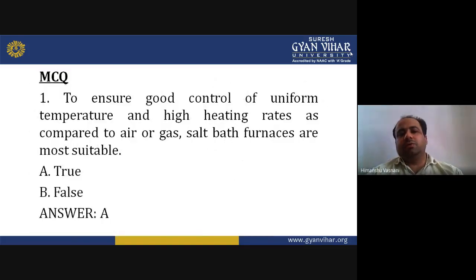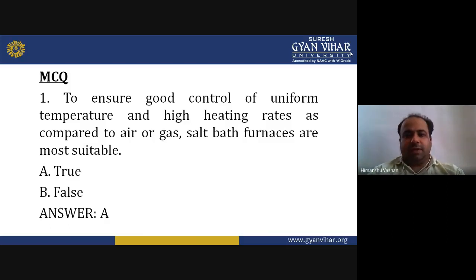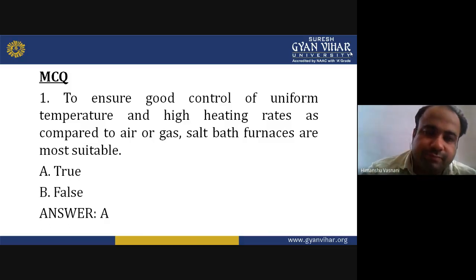Okay, now to ensure good control of uniform temperature and high heating rates as compared to air or gas, salt bath furnaces are most suitable. We have discussed salt bath furnaces in our previous slides. So there it was also said that if you want good control of uniform temperature and high heating rates as compared to air or gas, you can use a salt bath furnace. Okay, so it is true.